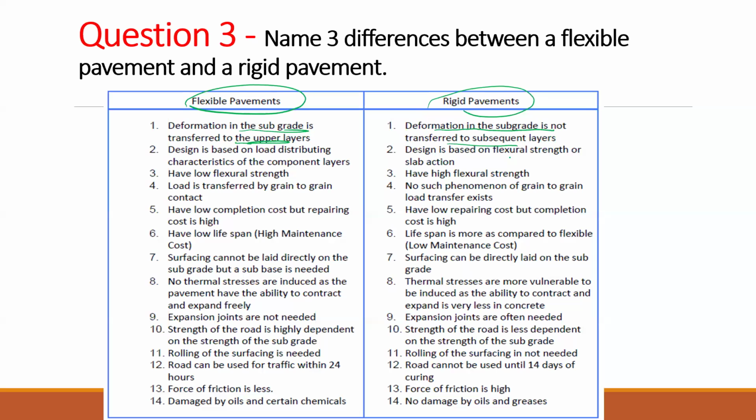But for the flexible pavement, the layers are not concrete, they're asphalt. So the load is transferring grain to grain. If something happens, like volume instability or moisture, to the native soil or the subgrade, that effect will come to the upper layers as well.